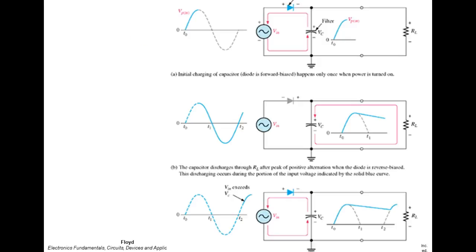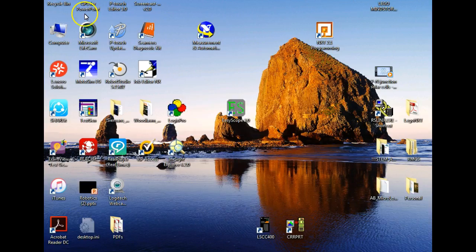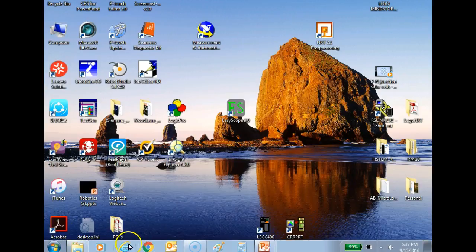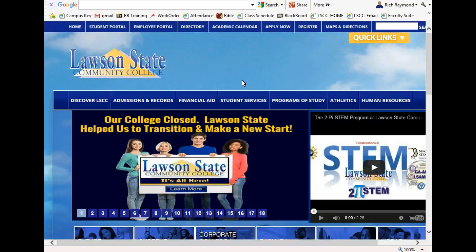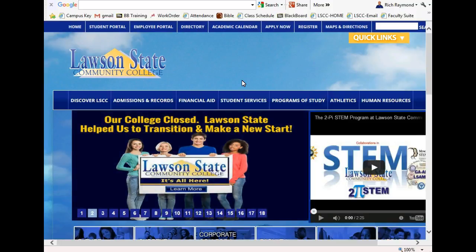So if you look at the data sheet for the 1N4000 series, which is what we're using, right? Then we look for what we call the surge current. And the surge current for the 1N4000 series is 30 amps. That's for a half cycle, but we're not even doing a half cycle, right? We're doing what? I think it's a half cycle.